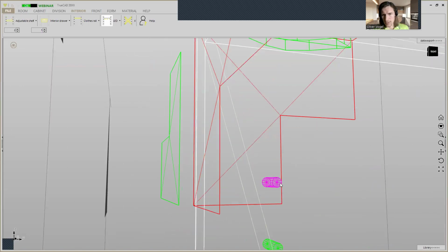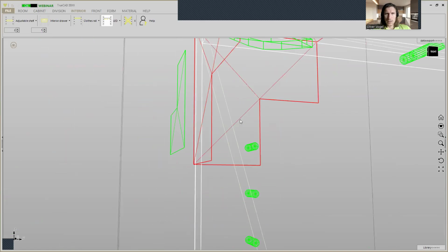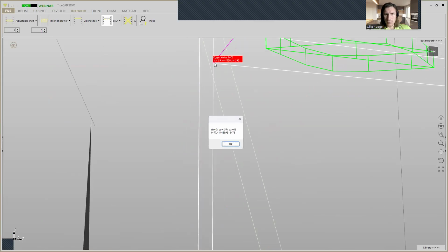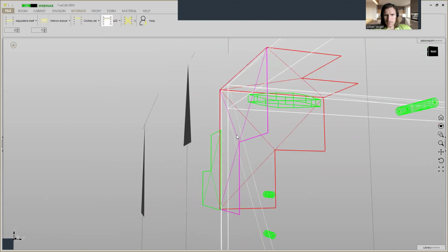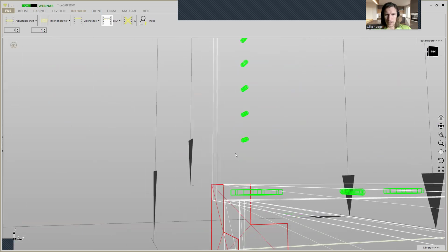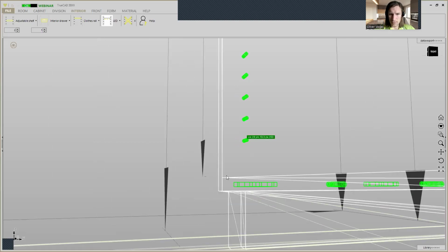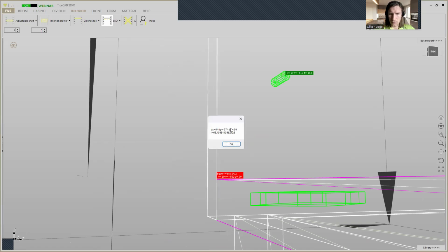When we go here in the center, keep the control button pressed. We see the red flag is activated, and when we click on it, it turns green. When we go to this point, you see DZ is 68. Now we are zooming in and also measuring, keeping the control button pressed, clicking the center of the hole, and here we have exactly 54.